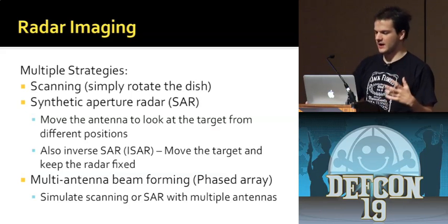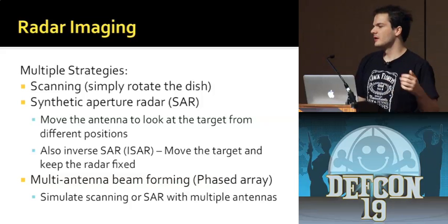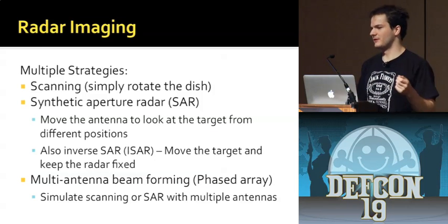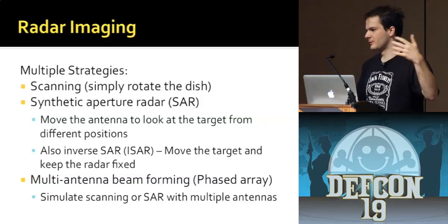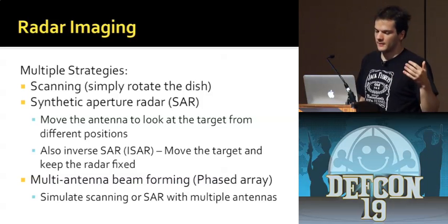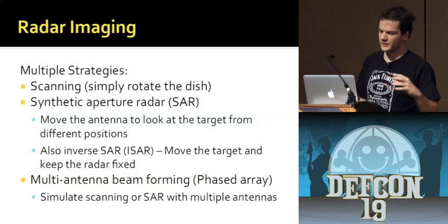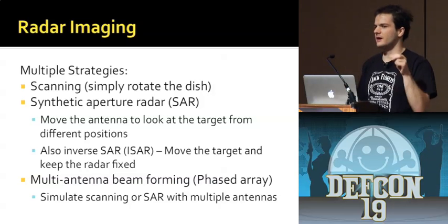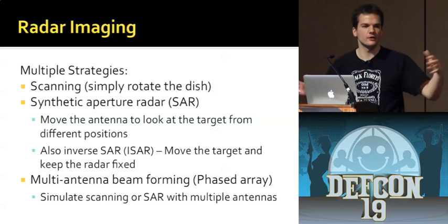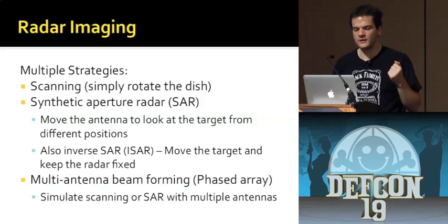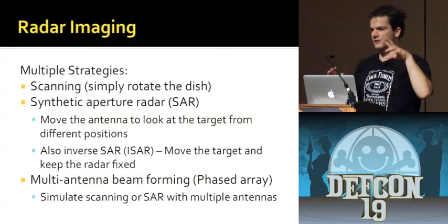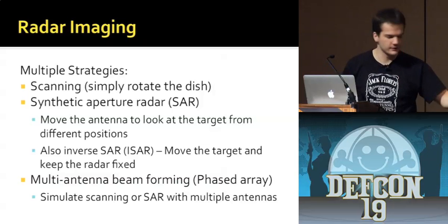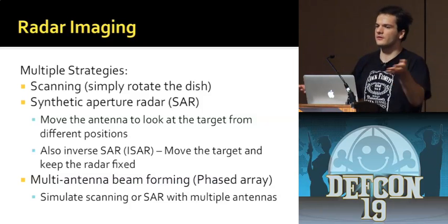There's something called Synthetic Aperture Radar, which basically means you can get better resolution if you have a bigger dish. But the problem is the bigger dishes are more directional, so that's the advantage. With synthetic aperture radar, you're taking coherent measurements of the signal at different places, and you're trying to simulate having a larger dish. The reason you would do that is so that you can get a finer resolution of space. If you just point it in one direction, I think the beam widths on these things are like 40 degrees or something, so you couldn't see anything out there.